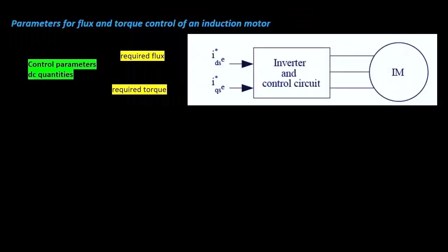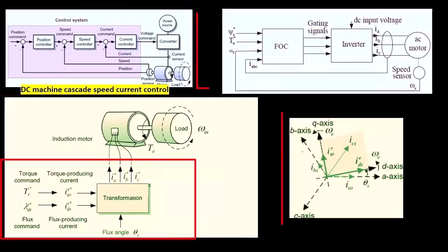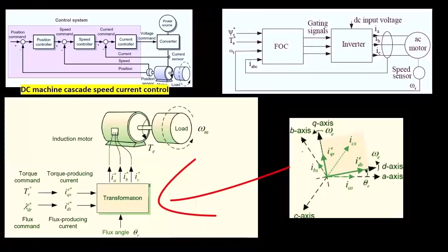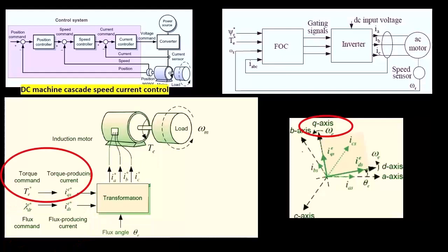The field-oriented control, often called the vector control, refers to all AC machine control methods that split the current vector into flux and torque components and control each of them independently. The basic control principle is the same as that of a DC machine, except for the rotating reference frame. The phase currents are transformed into a synchronous reference frame, whose d-axis is aligned with a flux vector. The d-axis current determines the flux magnitude, whereas the q-axis current, being orthogonal to the d-axis, controls the torque.